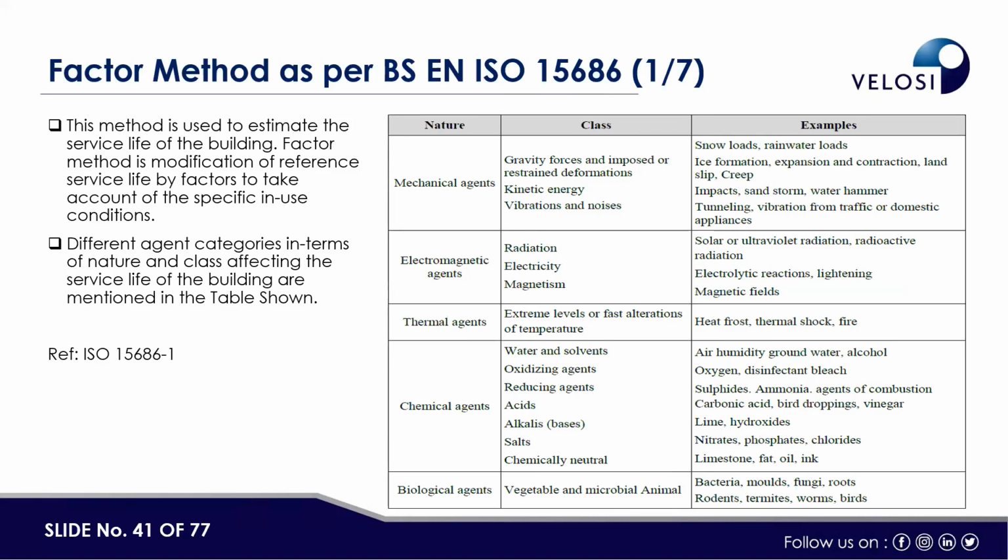Like once we pour the concrete, how we cure the concrete, what water cement ratio is used, and what admixtures are used. These all contribute to the overall life of the structure. So there are certain criteria that we set during the design phase, and once the structure is in service, we will have certain criteria to monitor the structure and take it further to its intended design life.